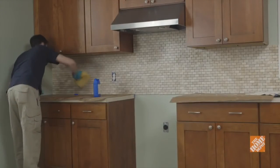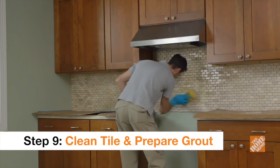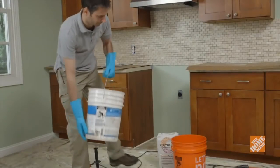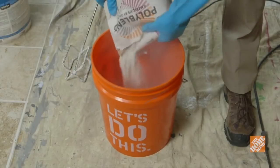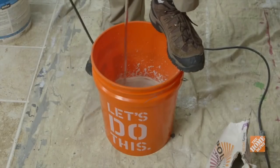Pre-sealer helps protect the stone from staining. Wipe the tiles clean with water before you apply polyblend sanded grout to natural stone mosaic tile. Carefully follow the preparation details on the package. Fill a bucket with the appropriate amount of water. Then, gradually add the grout powder. Mix it thoroughly. Let the mixture stand for 5 to 10 minutes, then remix it without additional water.